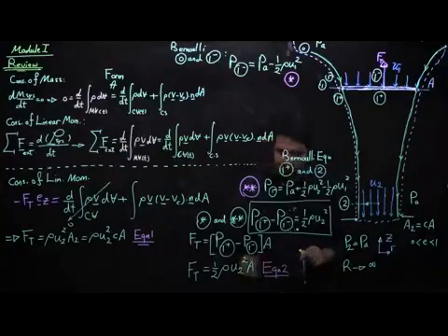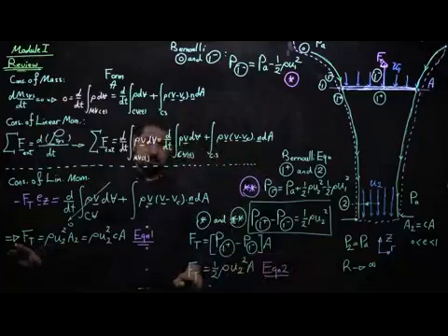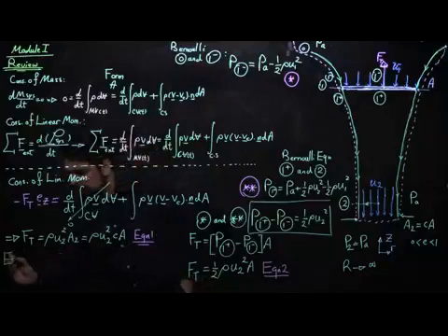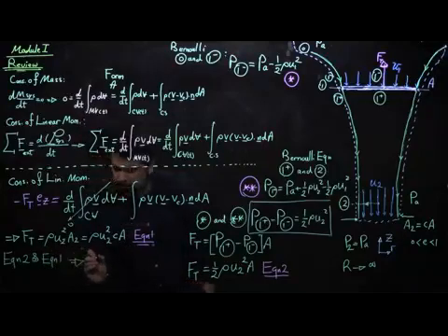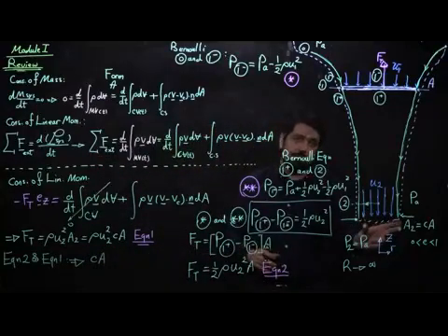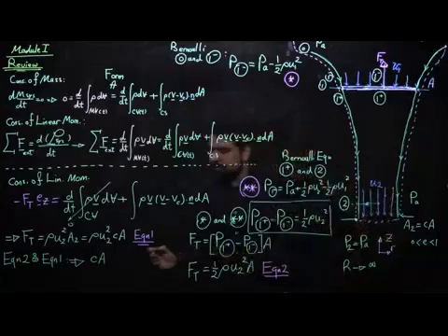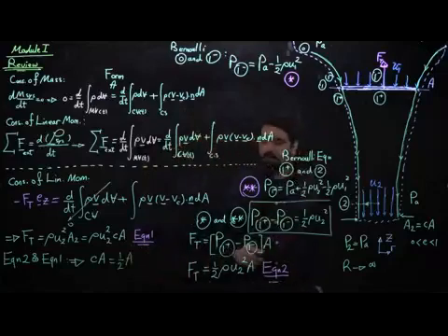Now clearly, equation 2 and equation 1 should give me the same thing because they are both two different descriptions for the thrust force. So if I combine equation 2 and equation 1, I will conclude that CA, the contraction coefficient for the area of the jet flow that finally comes away from the helicopter, in the position below the helicopter, should be equal to half of A, the cross-sectional area of the blade.